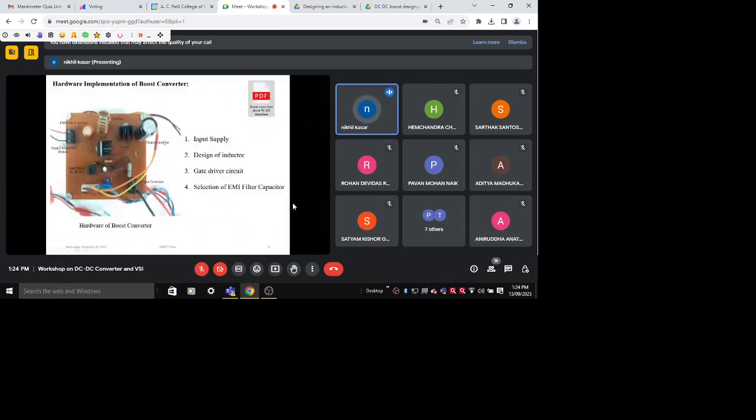Okay, so after the components, see this gate driver PC923. There is this 10 microfarad capacitor, this ultra fast diode UF4007, and this resistor is of 22 ohms. Okay, red, black, 22 ohms. This is the MOSFET, and I have also added a heat sink to this MOSFET. You can see the screw also. This is the diode, and to that diode also a heat sink is connected. Okay, this is the inductor, EMI filter, capacitor, and all of that.